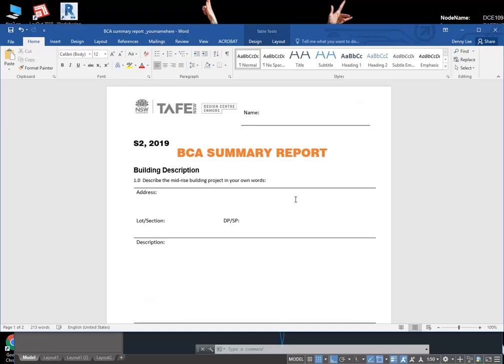Because I've got glass walls going through 2 stories, obviously they stop at the full level, but that's in their report. Do I have to say something? Well, look, if you're going to have concrete floors, then that's a really simple solution. It's terrible for the environment, but we don't care. For this, we'll just say concrete makes it easy because then you can have the fire separation between the ground floor and the upper levels, and that solves it. It's a simple structure. It's not simple to build, but it's simple to draw, and less work to document fire separation.